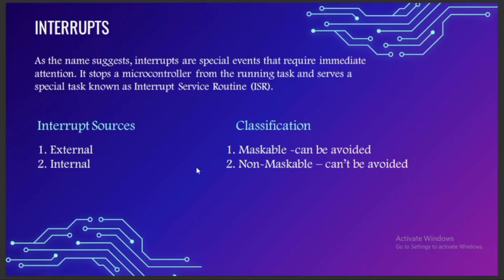Those are interrupts. What are interrupts mainly? Interrupts play an important role in a microcontroller. As the name suggests, interrupts are special events that require immediate action. It stops the microcontroller from the running task and serves a special task known as the interrupt service routine, ISR. ISR stands for interrupt service routine. Now, these interrupts are generated from a source. Every interrupt has a source, and the interrupt is generated from the source. Interrupts have two sources. The first one is an external source, and the second one is an internal source.